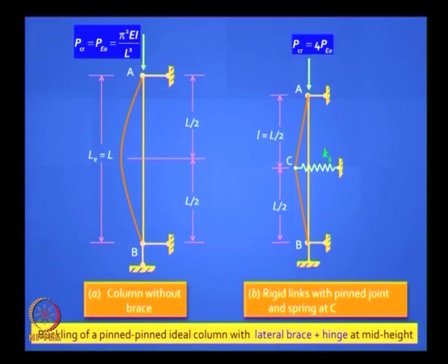Put a spring. You don't need to prove this. You have to provide a minimum stiffness for that brace, and that will guarantee this for you. Let's check it out. Let's say you provide a weak brace, low value of KB. How would you think it will buckle now? If I put a hinge there, then definitely it is going to buckle like this.